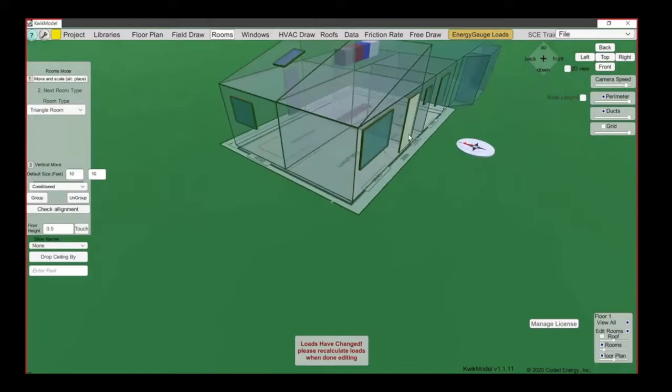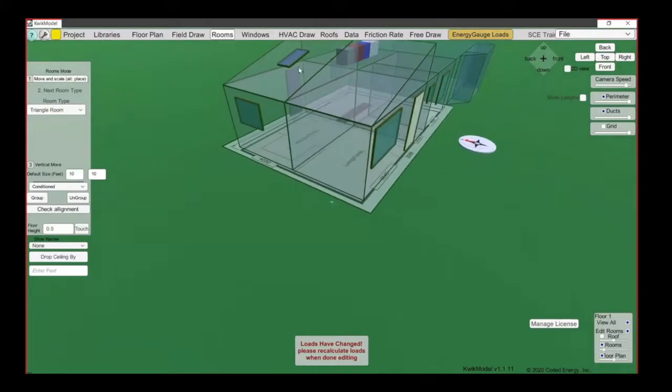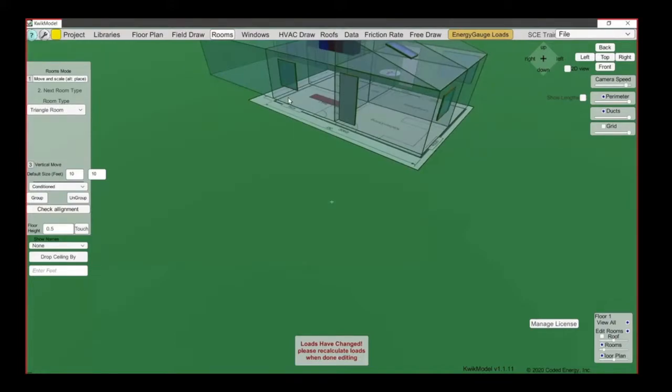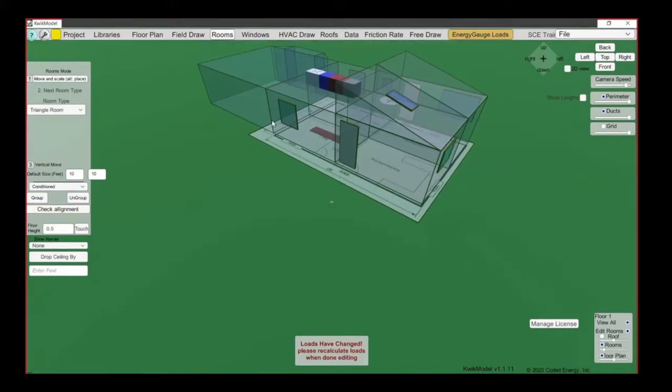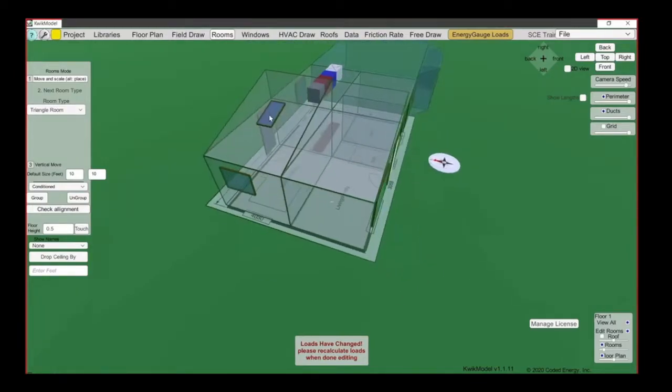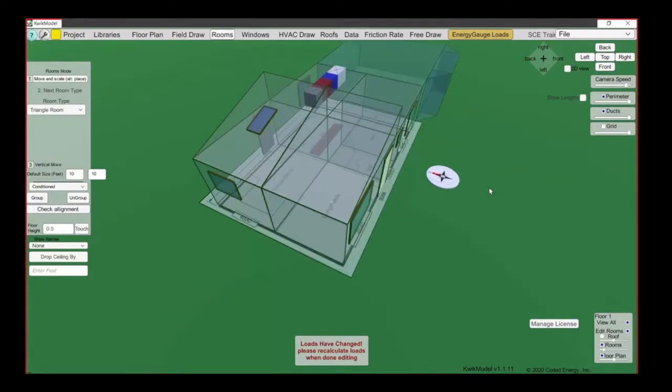But this window over here on the west, as the sun is setting in the afternoon, it's going to get some light just pouring through it. It's beating through that room. It's going to get hot because of that one little window there in the afternoon, okay? And on the back of the house, these all face north. They're rarely going to get any direct sunlight, okay? So, and then here, look at the skylight we put up here. The skylight is facing west, so the heat's really going to come screaming through that skylight there, okay?